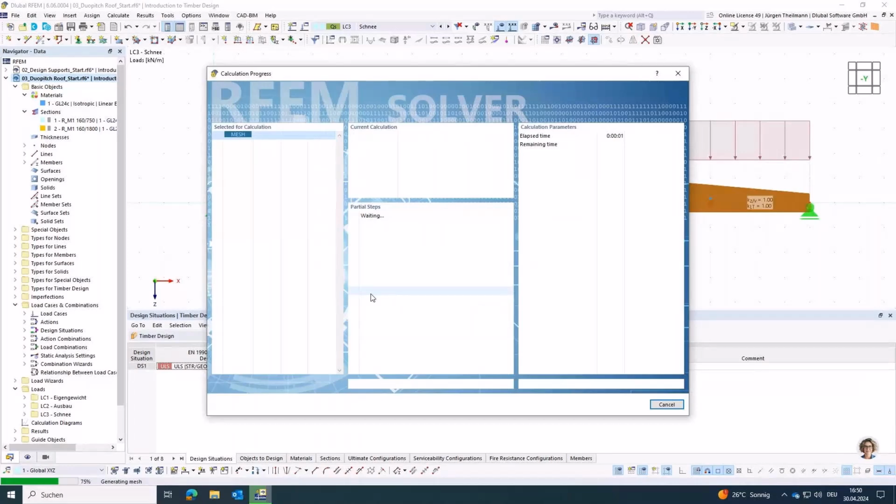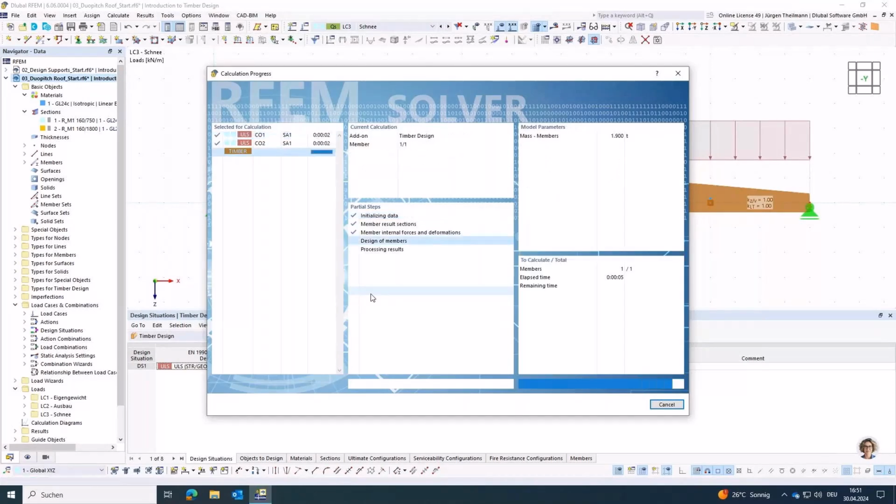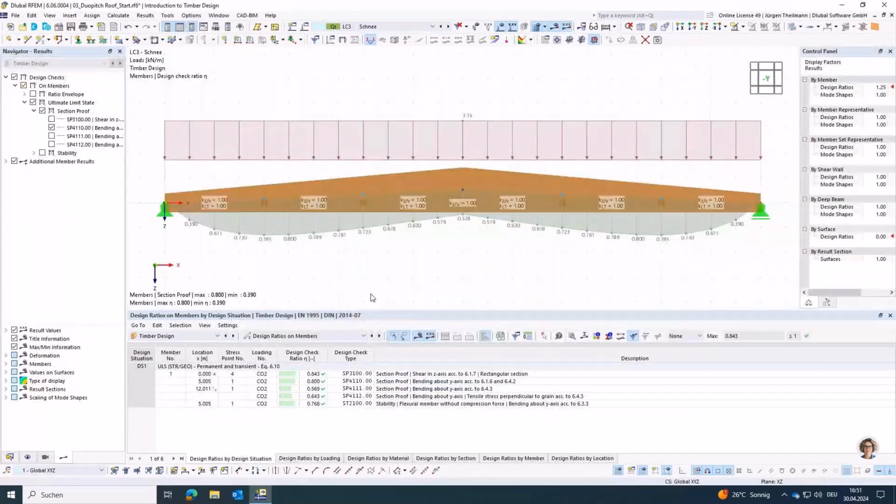And this is basically the same idea you also got from the training introduction to FE analysis, where you basically always say that you need to keep the mesh as coarse as possible, but at the same time as fine as necessary. Otherwise, you would have a maximum of the bending stress at this intermediate node, when in reality it's a bit more to the inside of the member.